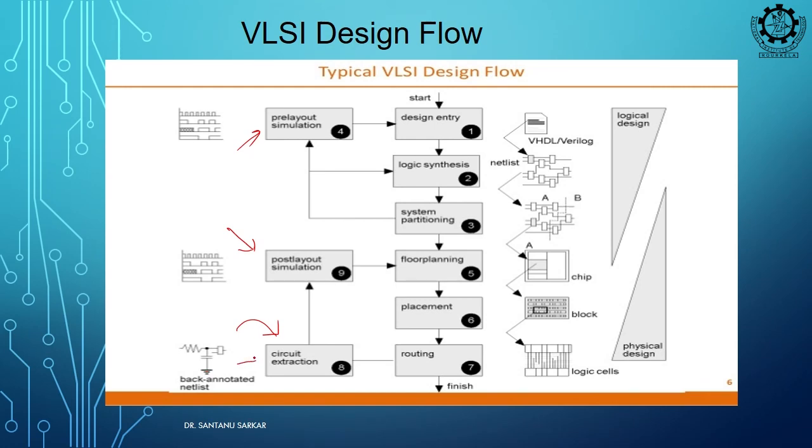This is actually what we are doing, we are trying to get a feeling of how the circuit will perform after fabrication. So this post layout simulation is the nearest simulation environment that you can have, to get a feeling that after fabrication this could be my performance, close to that. Even on top of that it will vary somewhat.